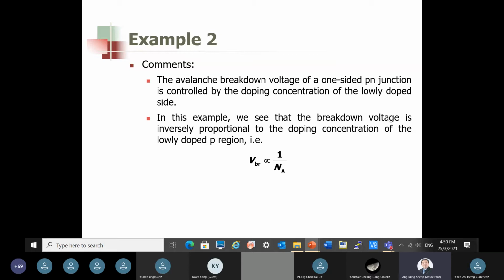On the other hand, avalanche breakdown is destructive because the current that flows during avalanche breakdown can increase very significantly and uncontrollably due to the onset of impact ionization and a chain reaction process that causes more and more carriers to be generated through impact ionization. Zener breakdown therefore has a lot of practical value.